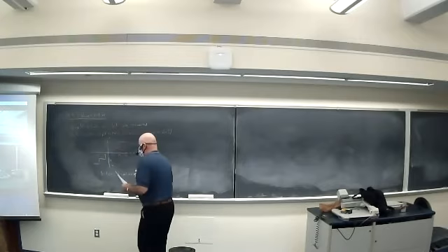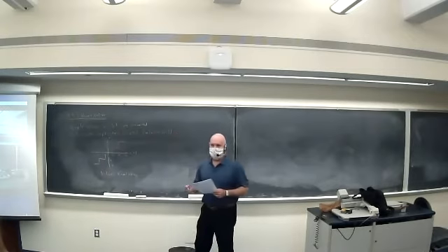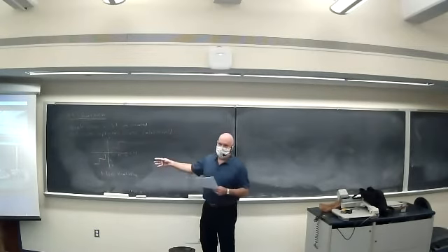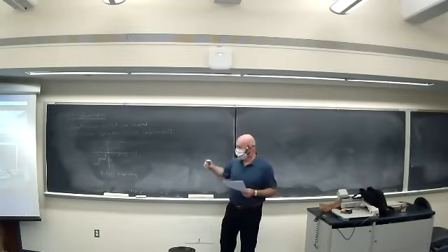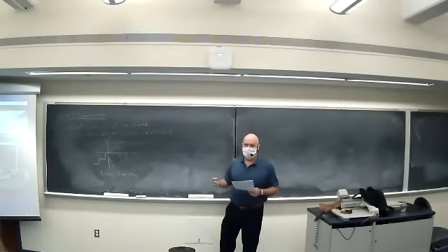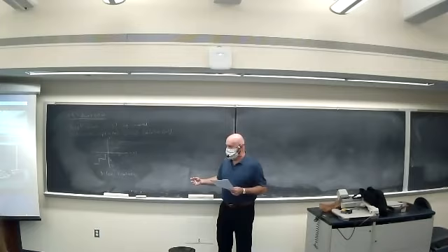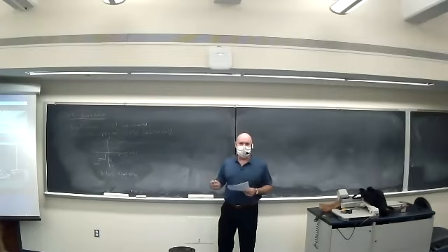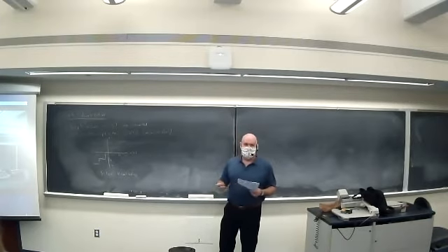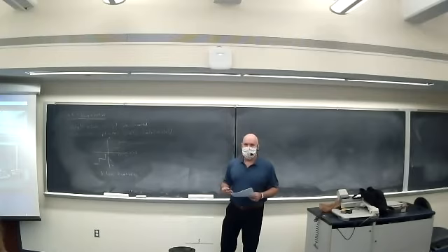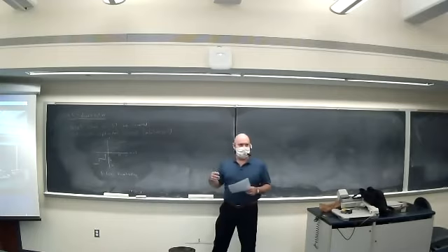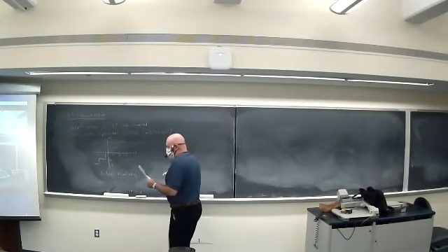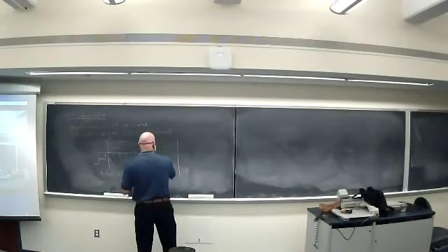Now, typically, the number of levels here is a power of 2. Okay. So you normally wouldn't see a 5-level quantizer. We'll talk about error, but there's a lot of error here. So typically, you talk about an 8-bit quantizer, which would have 256 levels, or 12 bits, or 16-bit, which is CD quality. Okay. But I'm not going to draw 256 different levels. So what happens now based on this?